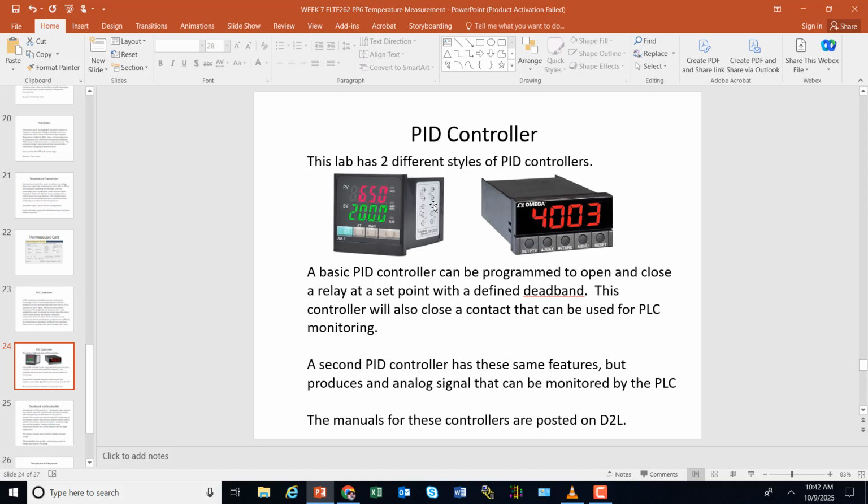I've got another meter that reads thermocouple, a multimeter, so we can compare it. And then we just want to take a look. This will turn on a relay, so we'll just have a light go on, I guess, and that light could indicate that, hey, we're turning on the heater or whatever. But this whole thing is something you can buy online for 20 bucks. You get a PID controller, you get a thermocouple, you get a solid state relay, and you get a heat sink. They're pretty cheap, right?